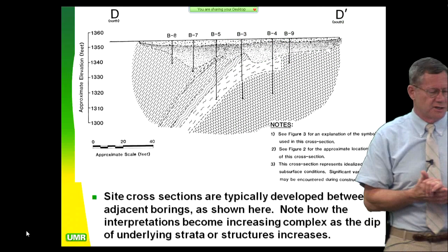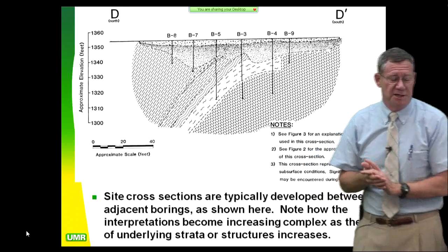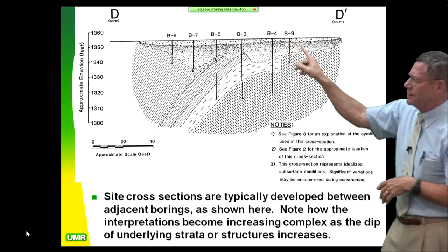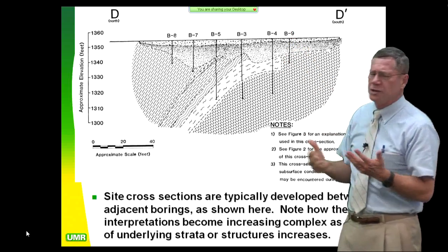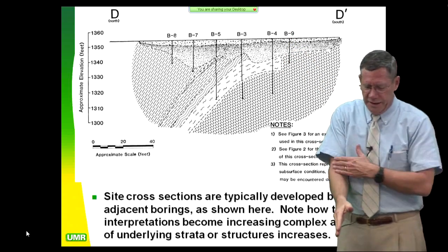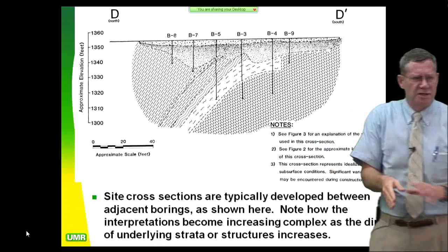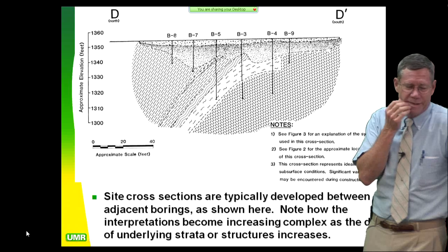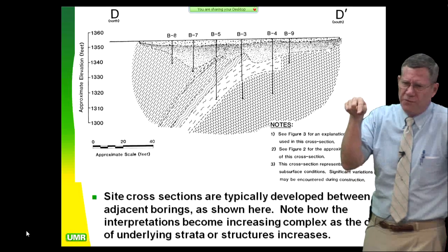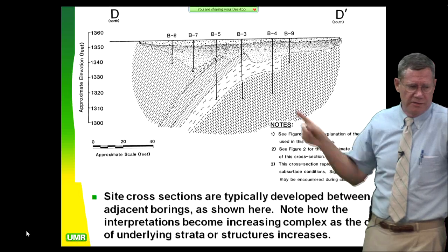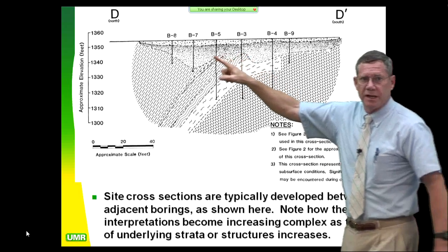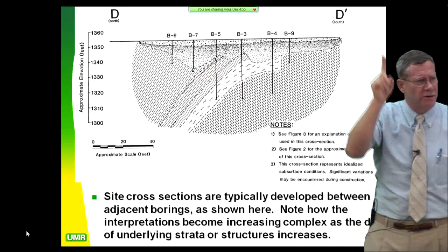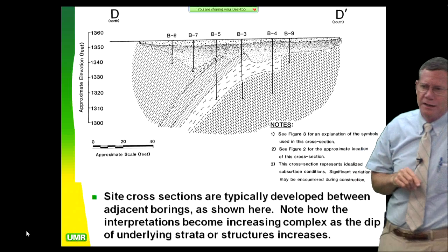Here's my first cross-section out of college. I'm drilling a bunch of holes along Grizzly Peak Boulevard up above the city of Oakland, California. And it's an erosion problem where we had a culvert that had a big storm. There was so much discharge going down this little culvert. I mean, it was like an 18-inch culvert or something. And it dug a hole 40 feet deep in this colluvium, in this material right here. 40 feet deep. That's a 4-story high building, much higher than Toomey Hall.